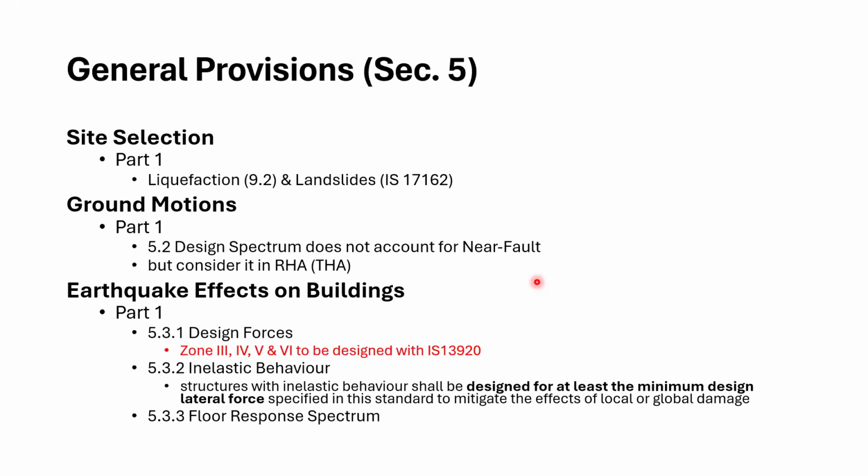And another update would be on the design forces and the design of members from zone 3 and above. Ductile provisions are applied, right? So inelastic behavior, and floor response spectrum in case of secondary systems, where there is equipment resting on these floors. So this floor response spectrum can be obtained from a time history analysis.